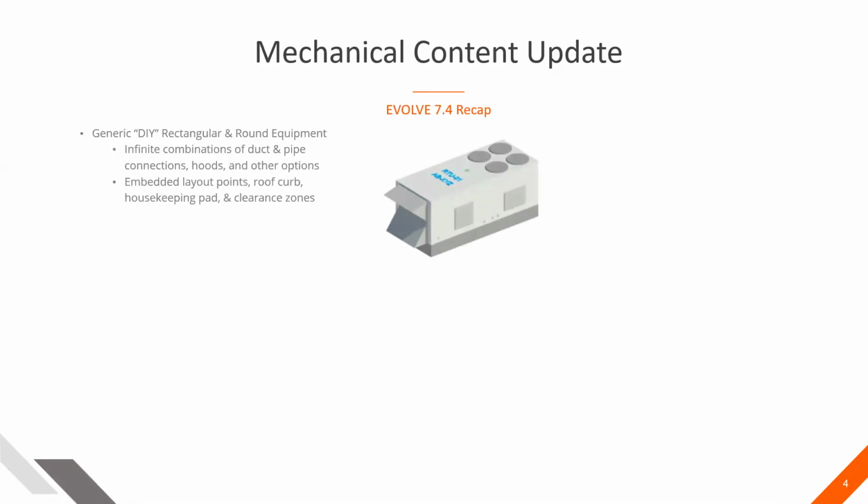So one of the big ones that we created was some generic DIY equipment. The purpose of this was to get the building blocks in your hands and make it easy for you to take a cut sheet, take a submittal, and build out equipment that works for you, that is lightweight, that looks the way you need it to look, has the dimensions that you need, and has the key features that you need in order to get your modeling done. I know the struggle of trying to find that exact BIM model for that submittal data, and you found one, but it's either old or whatever. We wanted to create a way for you to generate that yourself, and that's what that family does.